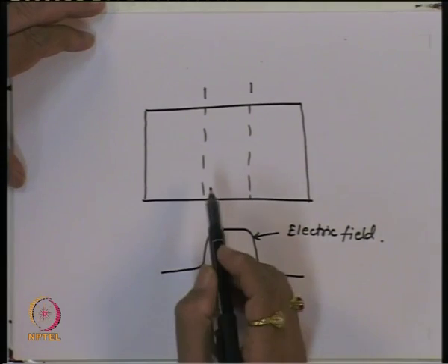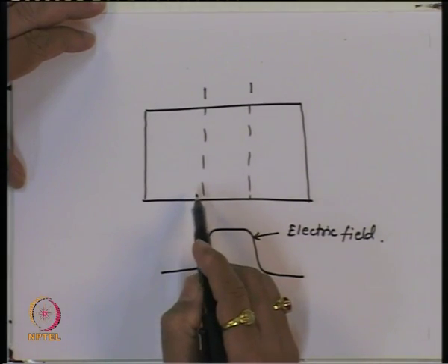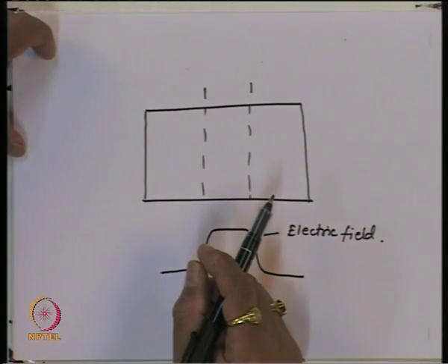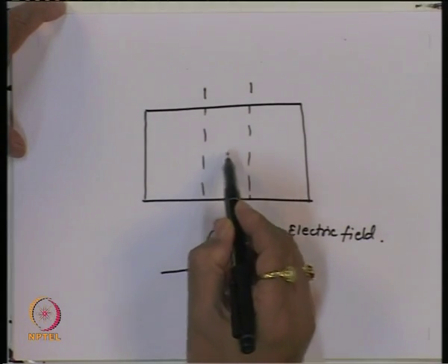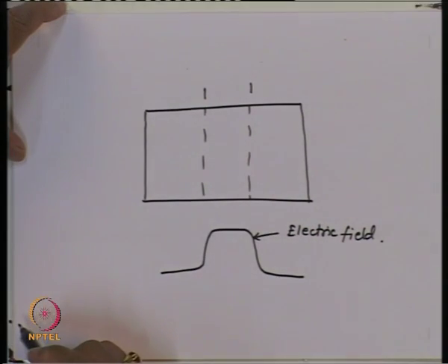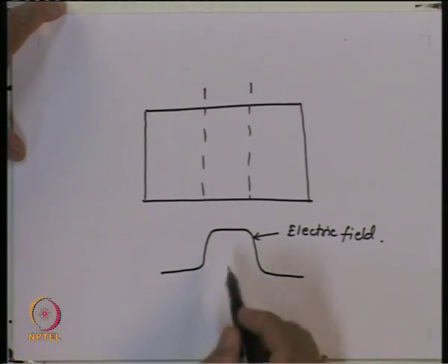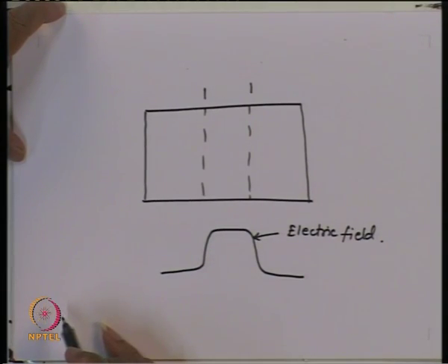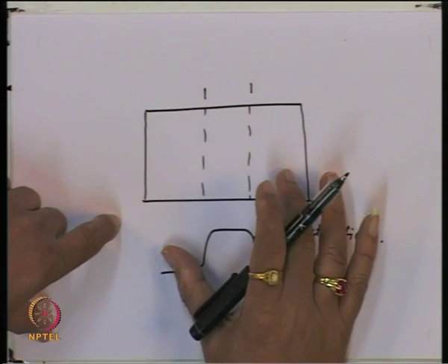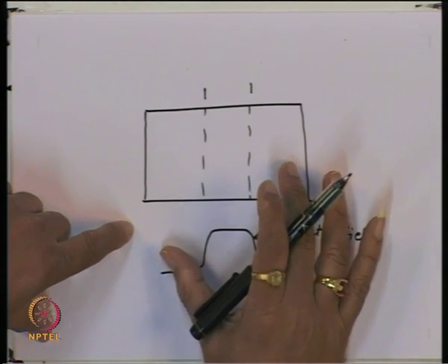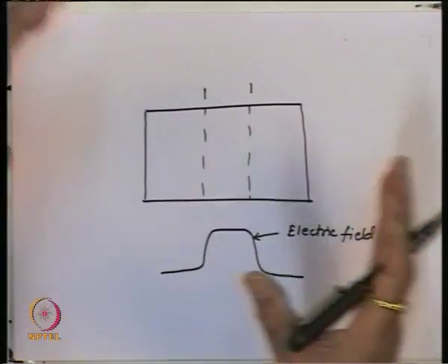Now, to make the absorption of the photon more efficient, the first thing we have to do is increase the length of this region, the depletion region, over which the electric field is practically constant. Also, since this device is a reverse bias device, we know that the depletion width varies as a function of bias voltage. So, we want the region over which the absorption of the photon takes place to be practically independent of the bias voltage.